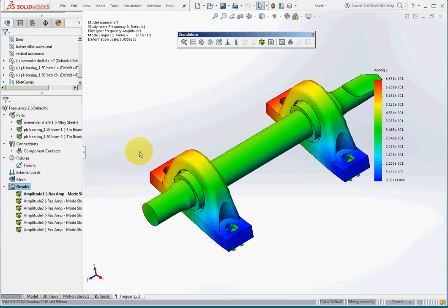That is because some of the fixtures are loosened and the natural frequency drops to a very low level, so we can hear the vibration sound. So theoretically, if you fix those bolts, the fixtures, again, the structure will be stiff again.